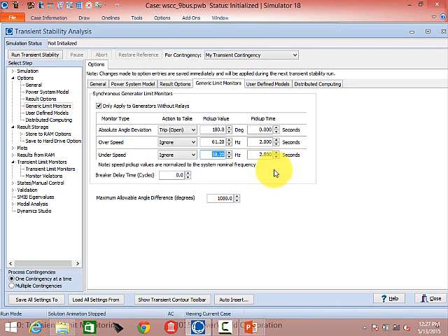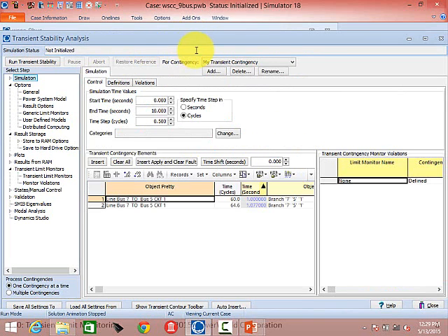Yeah, we did look to figure out the defaults, but I can't recall right now where we looked. They didn't just come out of nowhere. They didn't just throw some numbers up in the air and pick 61.2. Yeah, but they did change, and that's what I noticed, that they changed from several months ago. Oh, did they? Yeah, it used to be that for the underspeed it was 57.6, and now it's 58.2. And for the overspeed, it used to be 62.4, and now it's 61.2. I don't know why the values changed.